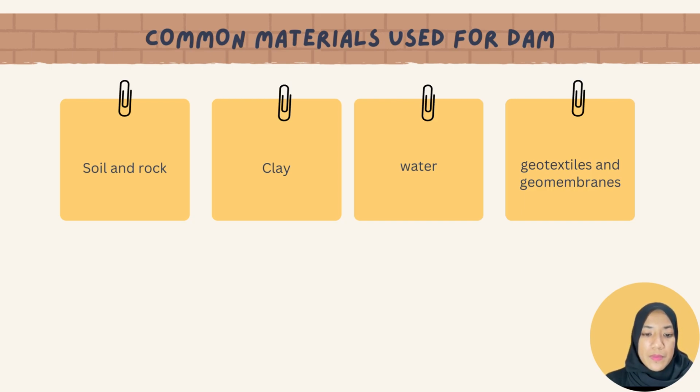The dam can be constructed with an impervious core or central zone that prohibits water from passing through if clay is nearby. Otherwise, the dam must be constructed with a diverse combination of materials that allow water to seep slowly and safely through its zones. Besides that, water is also one of the main materials. Compaction characteristics of the various soil types can be measured in a lab and applied during construction.